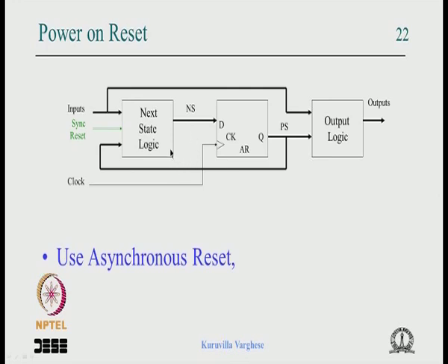When it is 1 the 0 goes, when it is 0 the normal thing happens. Okay, we have seen that kind of synthesis. Even if you write the equation, an equivalent circuit is going to come at the output. Instead of a 2-to-1 mux, maybe a simple AND gate comes, and the sync reset, if it is active high, can be inverted and given to the input of the AND gate.